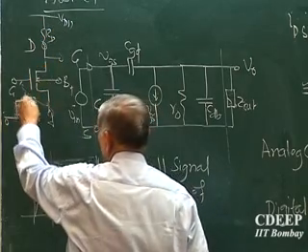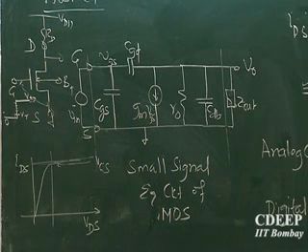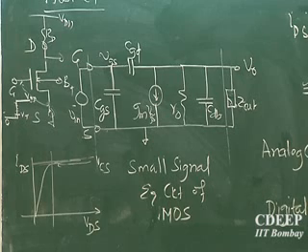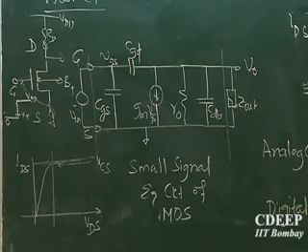Since this was VDD and you have just crossed VT, that may fall down, but still VDS will be larger than VGS minus VT. So the trick in digital circuit is, the device wakes up in saturation. Wakes up means when it turns on, it actually enters saturation. It looks a little odd from our characteristics, because if we are saying that it should go from linear and then go to saturation, the device actually wakes up in saturation, and as input rises, it enters non-saturation.